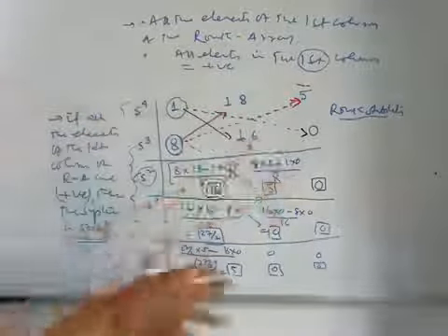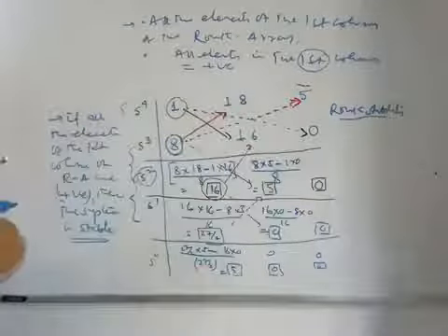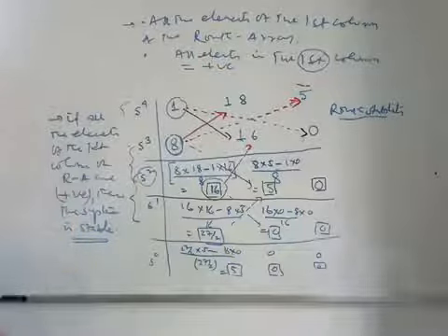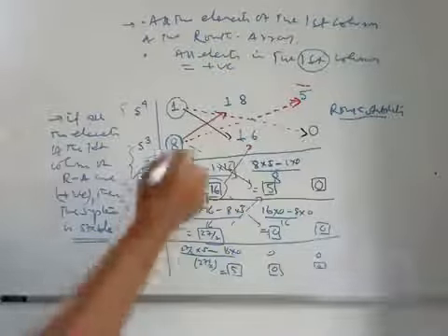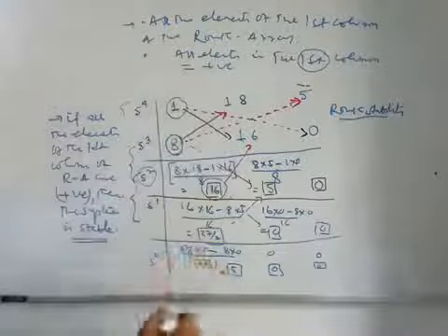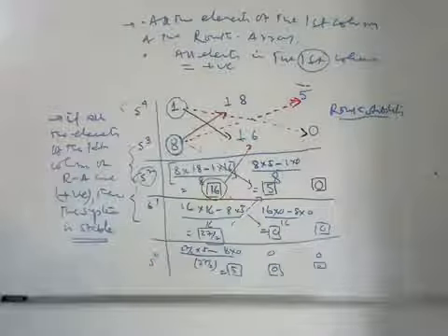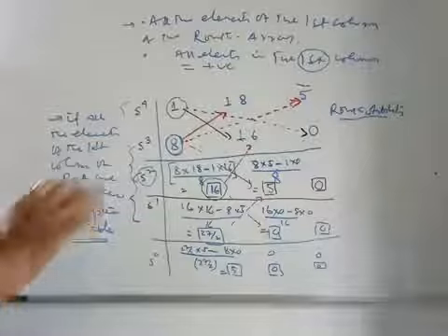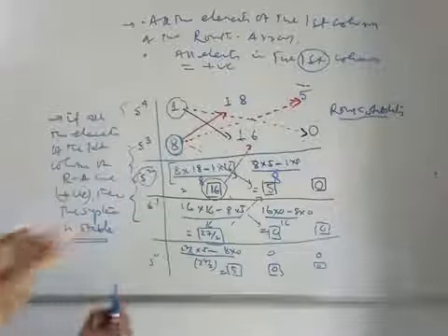So according to this, the system I have considered is definitely a stable system because there is no negative element in the first column of the Routh array. Okay, I will rewrite only the first column elements and I will explain something.